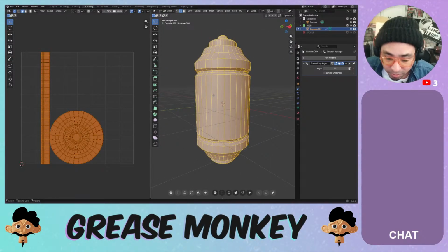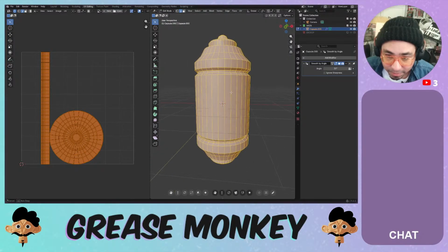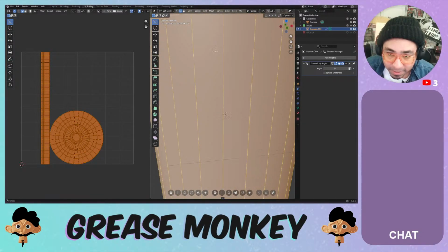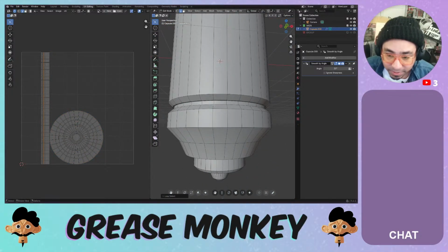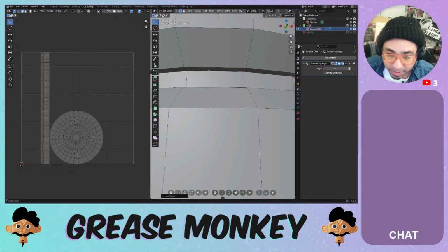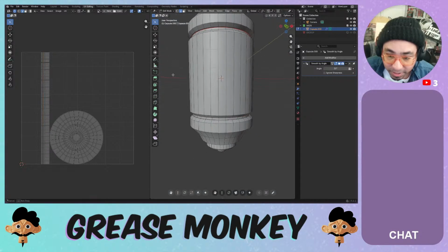And then we're going to unwrap this, but we're gonna unwrap this maybe in a better way. I think we could probably unwrap it from this point, this point. We'll do Control E. We'll do mark seams, so you'll see that they turn red there.